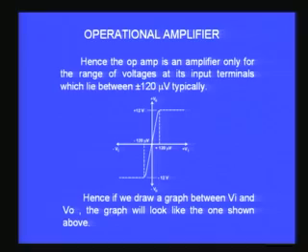But we already saw that for a typical real operational amplifier, this is not the case. You will have a small offset voltage, and therefore, this will not exactly pass through the center. Only in an ideal case will it pass through the center. So, this plus or minus 120 microvolt limit is very important to remember.